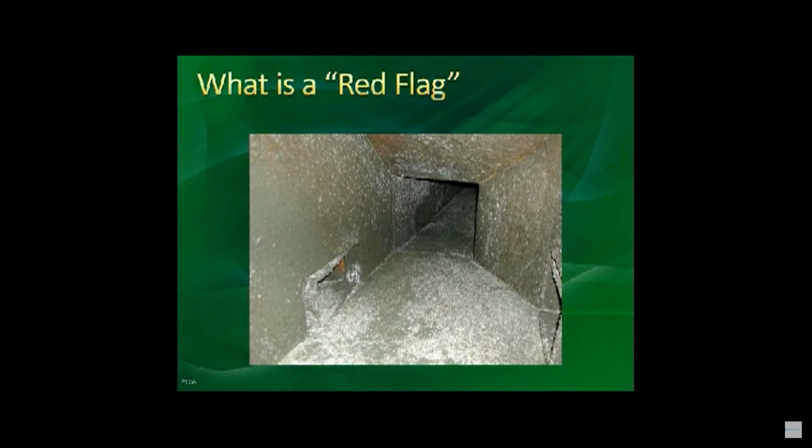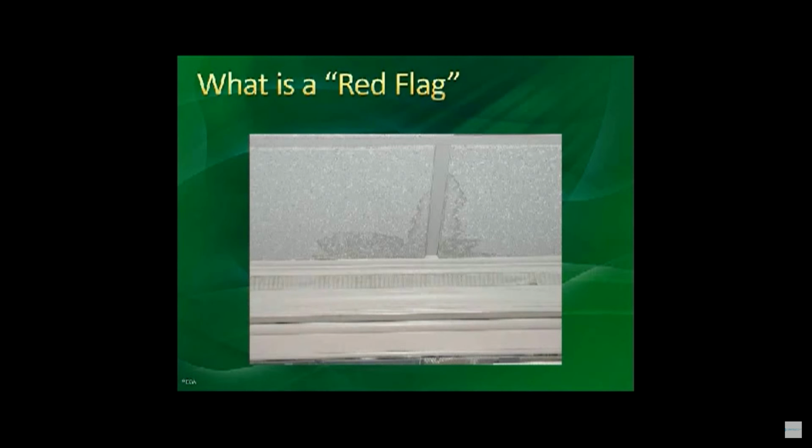Simple water stain on the ceiling tile. At this point, this is an active moisture stain. Could there be mold above it? Could there be mold behind the wallpaper that's curled and the wood trim? There could be, but also I must inform you about protecting yourself. If you take on the liability to pick up that tile and look behind it, make sure that you have an intrusive agreement signed with your client in case that tile becomes damaged. Wet tiles are very, very, very brittle.